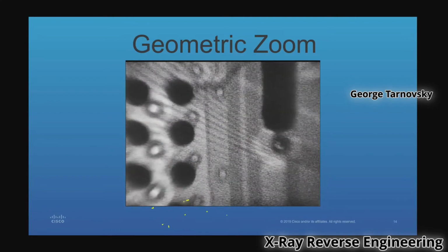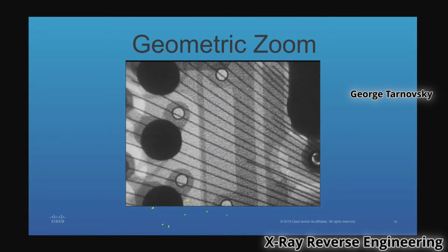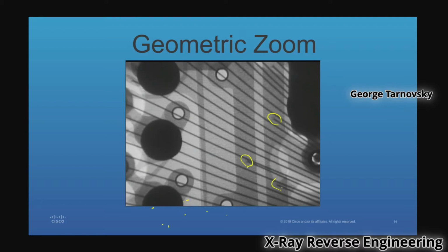Okay, so you can see how grainy it is because we're only sampling 16 times. Now, once we get to the final, we're sampling 256 times. You can see the signal to noise is improved, and there you are. You can see the bond wires clearly. It looks like there's a disconnect, but it's not. They're actually bonded to these buses. That's why they're there. But you can clearly see it, which is pretty unique.